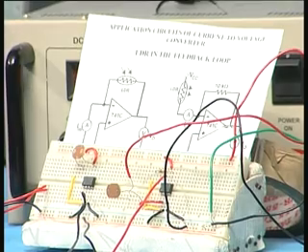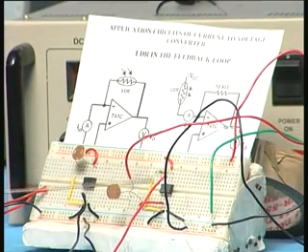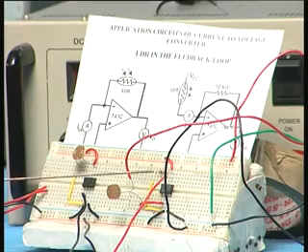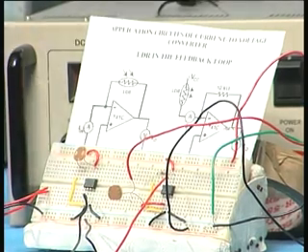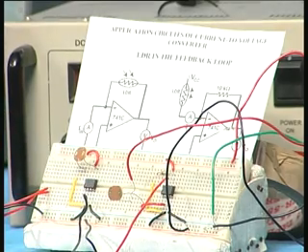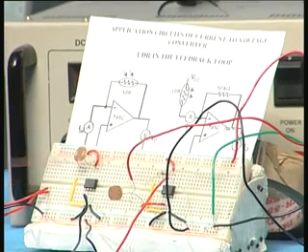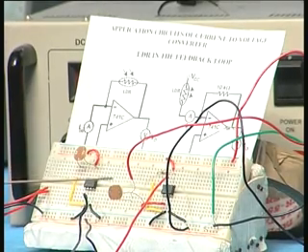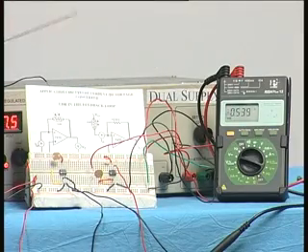So now you can see I have connected the multimeter to the second circuit, at the output of the second circuit, pin number 6 of the second op amp, and therefore you can see the current now is due to this LDR. The current source is due to this LDR, which is now exposed to a lot of light, and therefore the resistance is very small. You have large current, and therefore the voltage here is around 0.538 or so volts. It is in volts.